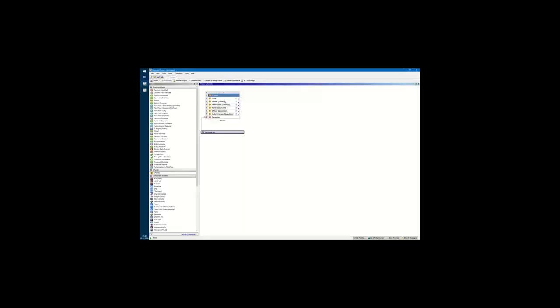So in the next step, we are going to link our exports of our turbomachinery design to the corresponding systems inside of Ansys Workbench. This can be done by selecting the export cell, performing a right click, and choosing transfer data to new. And we are going to link TurboGrid exports to TurboGrid systems.